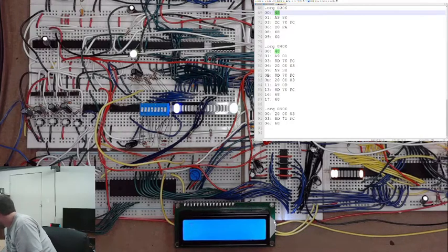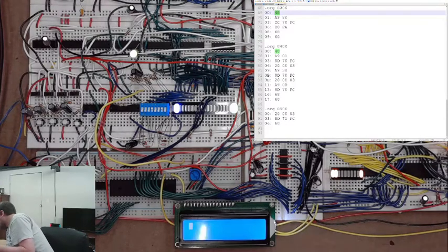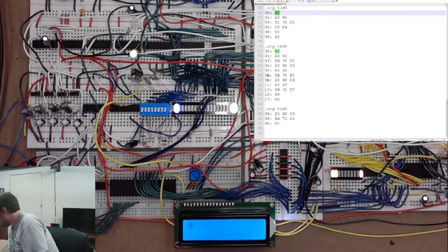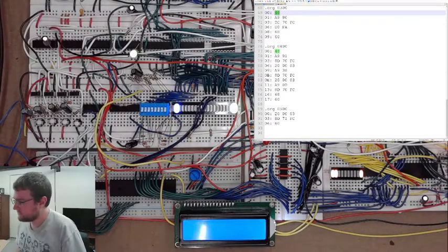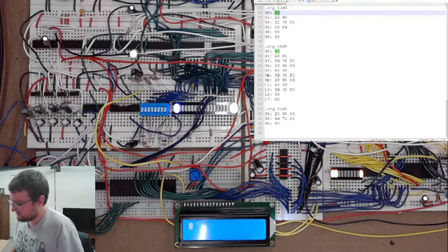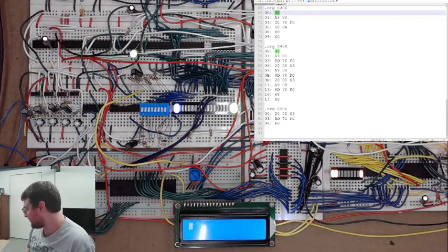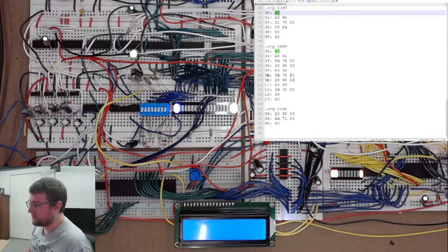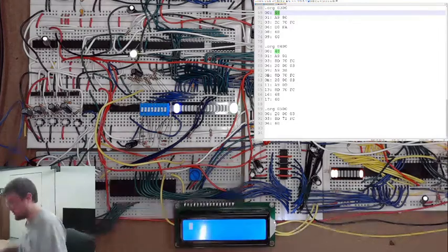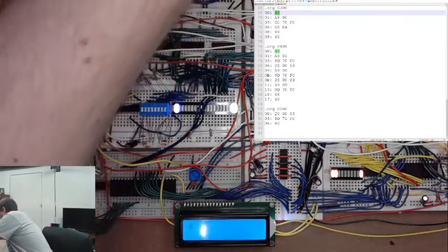Let's see, so I need plus to ground up here. Is there an easy way? Not really. Yeah, that is very true. Though maybe if I regulated it a bit, well, I'm regulating it with the capacitors, so it should be fairly regulated. I could have built it into the board. I haven't yet. And I don't think I will for the breadboard, because everything runs at 5 volts. No need to.